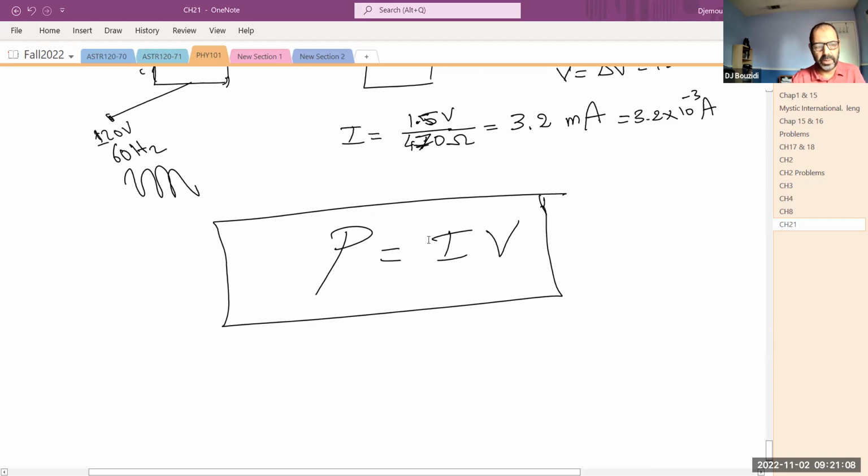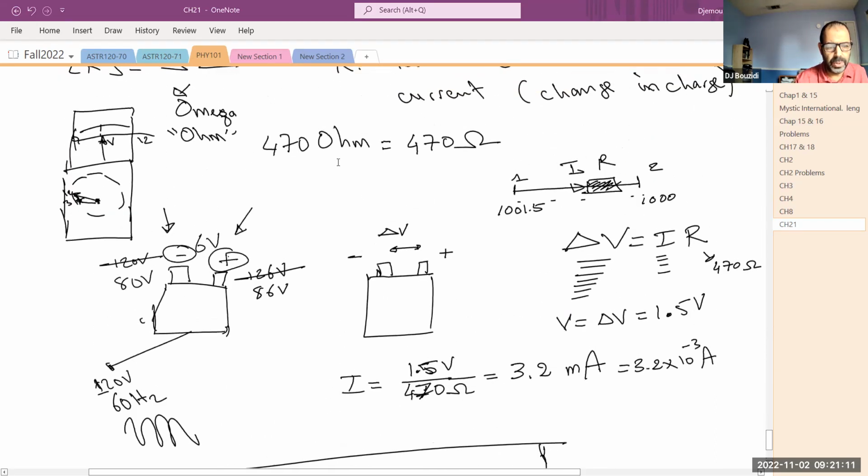One more thing before I forget in here, okay? When you guys were using the ohm meter, you could connect it directly to the battery. I could have a multimeter, I actually have one downstairs. You could connect it to the battery, and it's going to give you a reading. If the battery is still good, it should say for this one, 1.5 volts. If the battery starts to drain, it's probably going to read less, 1.4, probably 1.2. And by the time it's 1.1 volt, this probably will not be useful. You're going to replace it because it drops so much that it's not going to be a good battery anymore.